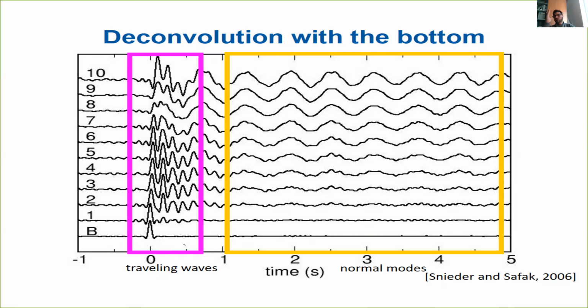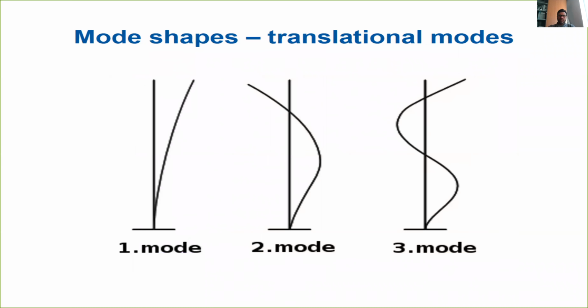So this is strongly related to the first mode of oscillation of a structure that we have seen yesterday. Exactly this one. So as we go up, the amplitude of shaking is increasing, but the frequency is always the same. It's independent of the position inside the structure.